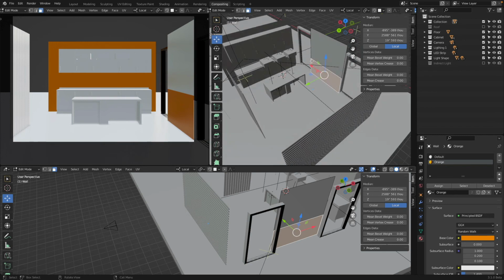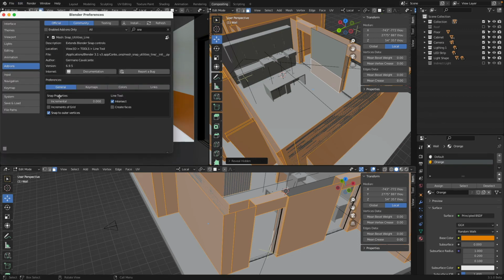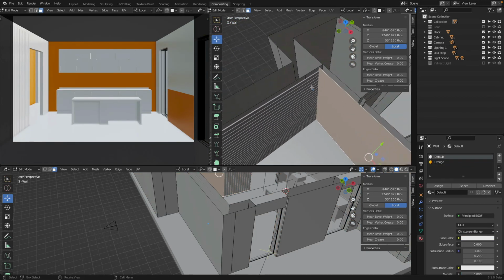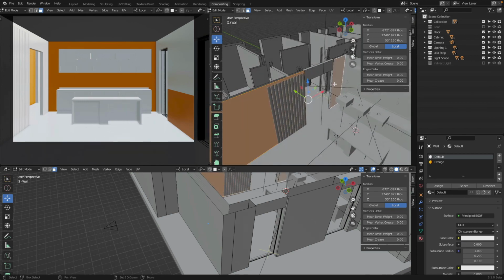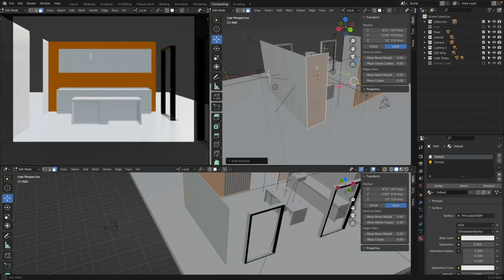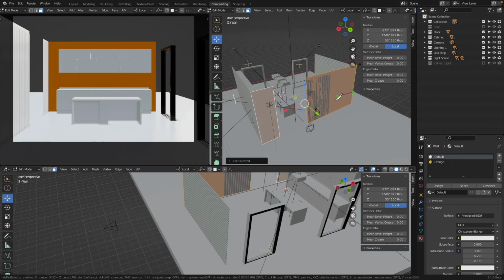And I press Alt-H. I would like to do one quick check. So yeah, snap utility. Yep, it's there. Okay, good. So if I select this face and maybe, yeah, maybe let's work on this face and this face. So Shift H, I will isolate these two walls. Again, I can press K, click, press X, and click and enter. K, click, press X for the X axis, click and enter.